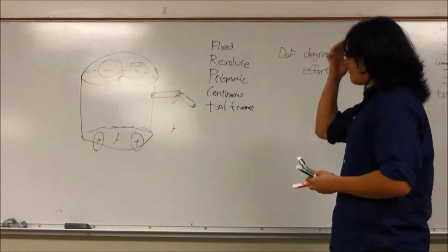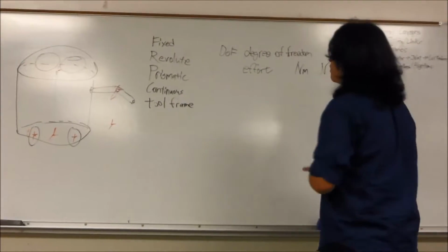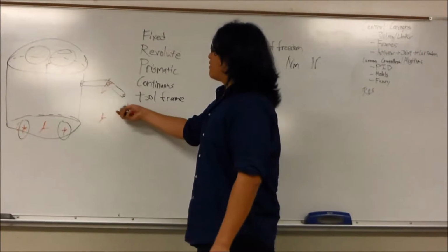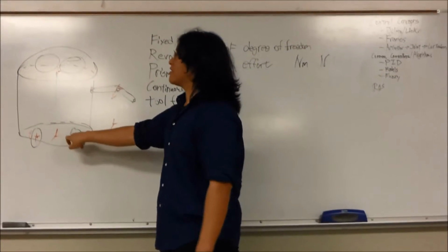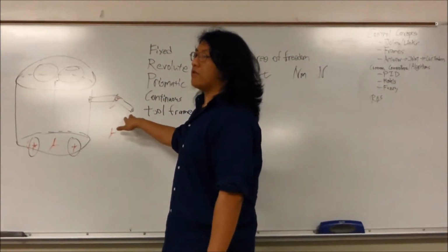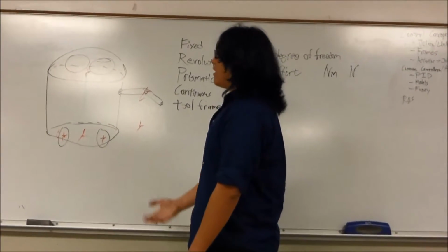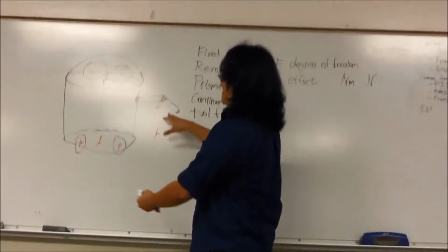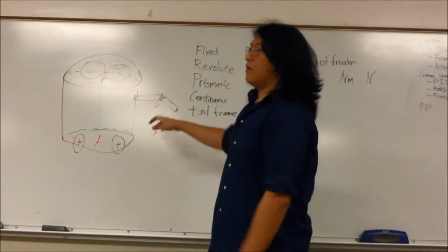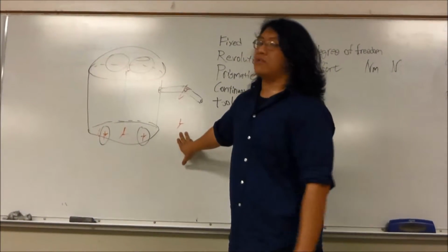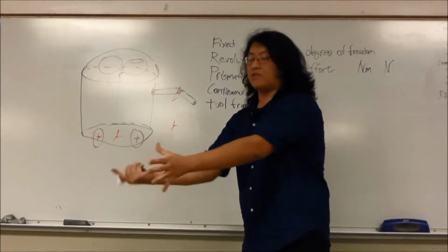This is the frame of your end effector, which in a lot of concepts in robotics, you're going to try to control the end effector of your robot rather than controlling all these joints and your wheels in order to make your end effector do something. And a lot of robotics control revolves around coming up with algorithms for how do I position these joints and maybe move these wheels in order to get my end effector to a specific world fixed location, right? Because I've identified there's this object I want to manipulate in this world fixed location.